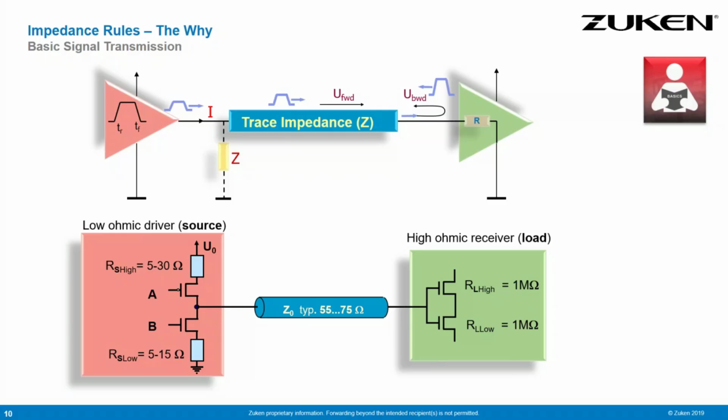And if we look into the CMOS silicon structure of such an interconnect, on the driver side CMOS shows an output resistance during the switching state. This output resistance is somehow dynamic. So we have an output resistance changing in the high transition from 0 to 1 between something like 5 to 30 ohms. While switching from high to low, we have an impedance of 5 to 15 ohms. Same as human beings: for us, it's easier to go down a staircase rather than moving up.